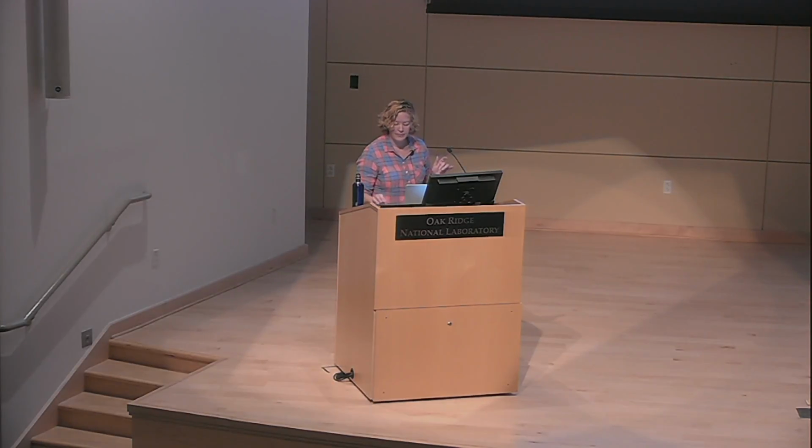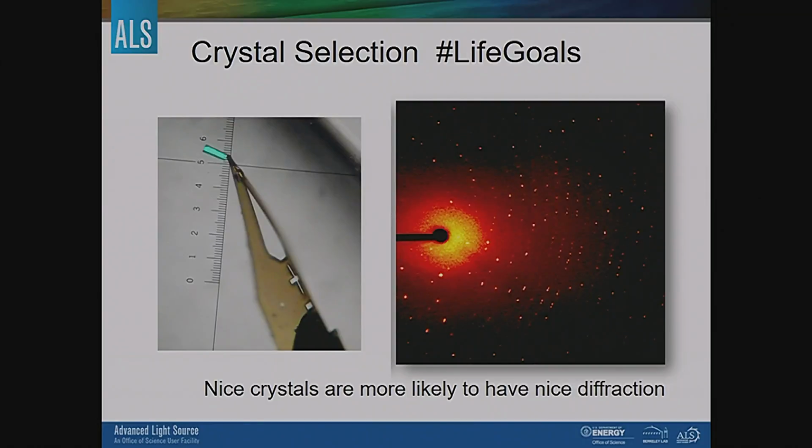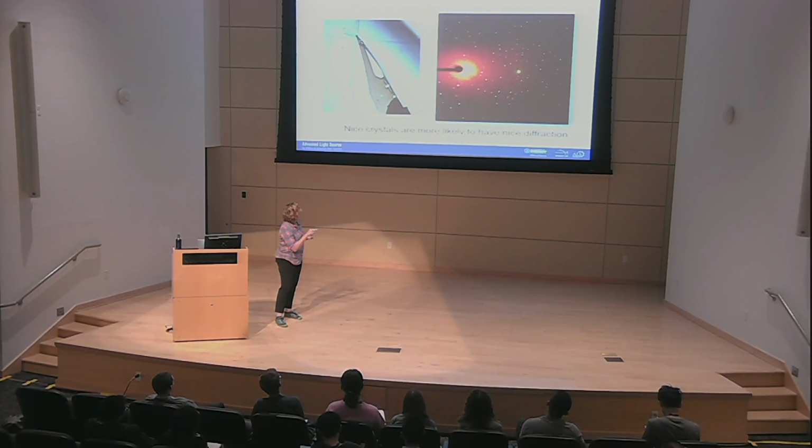This picture, this is actually a twin. So right there, you see those two spots next to each other? They're next to each other because they're two different domains. So ideally, in a crystalline lattice, you see spot, spot, spot, spot, regular intervals, never too close to each other unless you have a really long repeat in one axis direction. And then, if you do have a long repeat in one axis direction, you will see the spots proceed in a line. But the fact that this guy looks a little bit off from the general line of spots progressing there, immediately, twin. And it was a twin. So yeah. You're saying it's from a different domain? Yes.